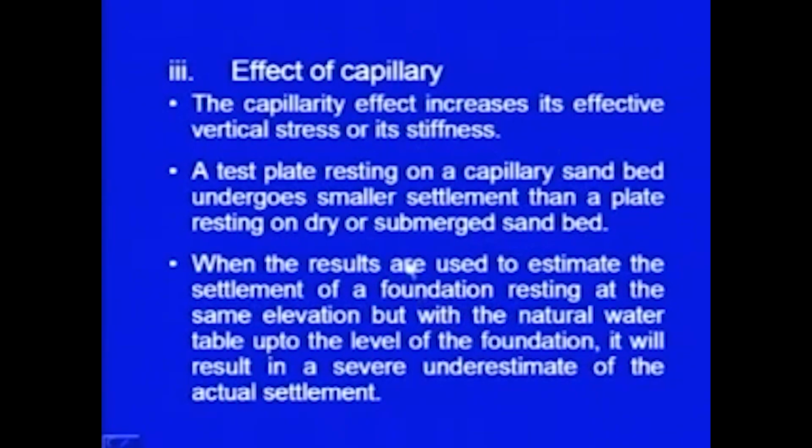The next point is the effect of capillary. As you know, the capillary effect increases the effective vertical stress. Due to capillary, there is negative pore pressure which develops in the soil mass. So, that results in increase in effective stress.